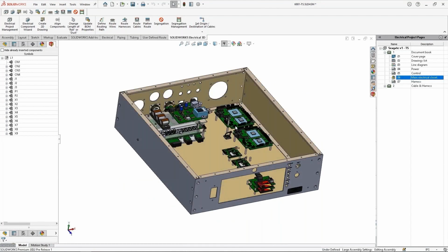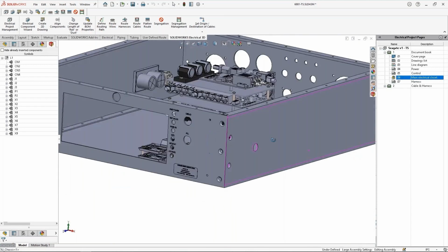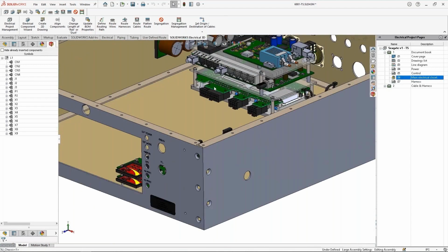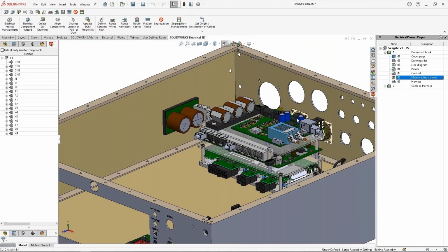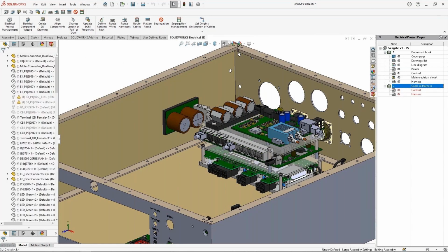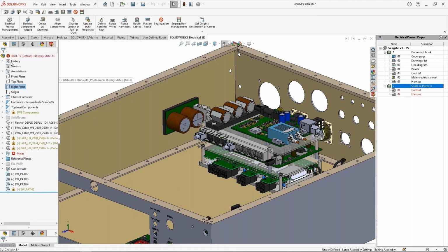So coming back in here, guys, nothing new. We already looked at this in the context before, but several connectors, several pieces of equipment, and smaller boards inside of this chassis. Now, mechanical, as I said, started with this workflow. So he's already placed his components. Given the fact that he has access to my project, you can see over there, those drawings are in red. That indicates electrical is working on those live, so he's getting real-time feedback. But we got our model tree over here, which is typical for mechanical.